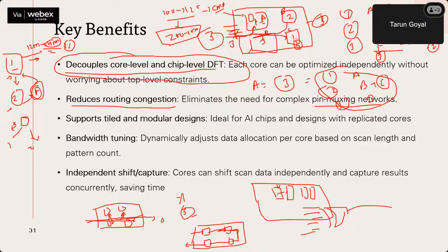So this is very good because now all are physically the same. You can apply the same data to all tiles. Even though you don't need new data, you have a bus, you apply the same data, and SSN supports that, and it compares on chip all the tiles' data and gives you the pass fail. If it's a good die, it's a pass. Take it, ship. If it's a fail, then it's just a failed die.